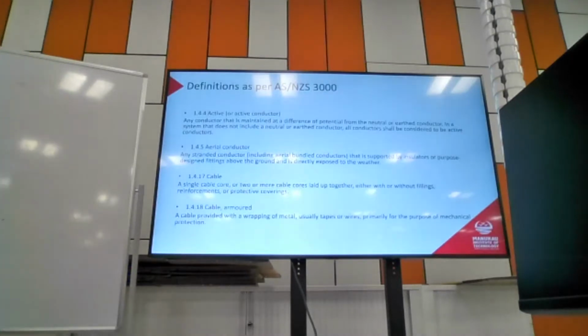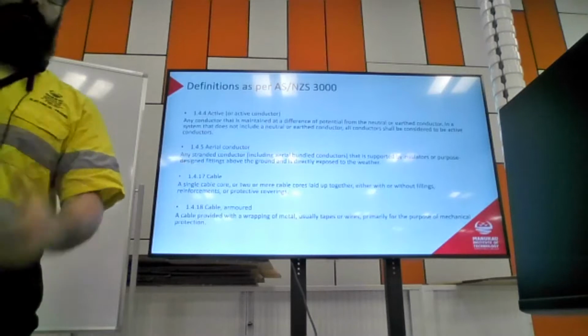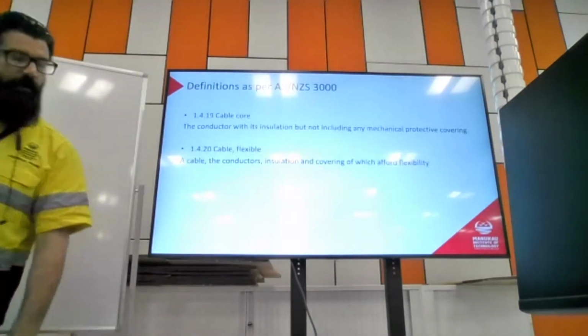Those are the kind of cables you would bury in the ground directly, maybe in a high traffic area, to prevent mechanical damage to the cable. And also you'd use a steel wire armored cable rather than running something in conduit maybe. If you don't have steel wire or any sort of armored cable, then you run the cable in a conduit to provide your mechanical protection.